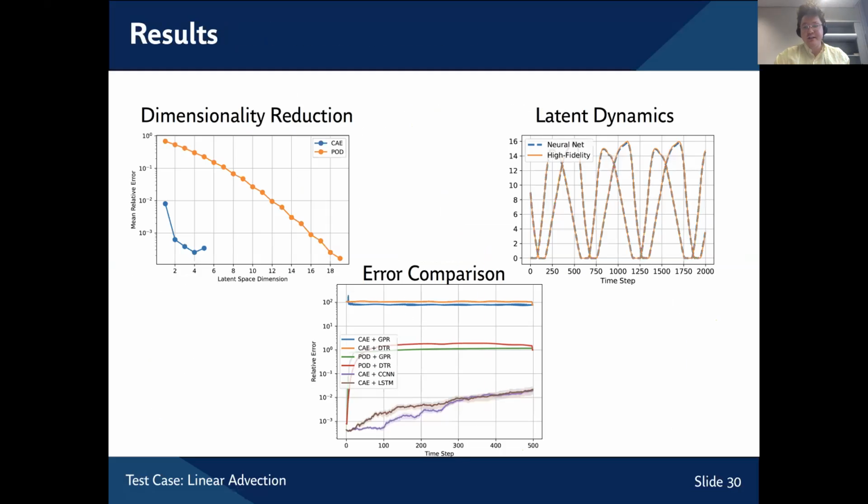Yeah, I do see a slight phase error growing in time. So in the advection equation, I noticed in earlier iterations of my training that the phase error was in general the problem, that the phase error grew. In this simple case, well, definitely not completely overcame it, but to a very large degree overcame it by doing a hyperparameter tuning.